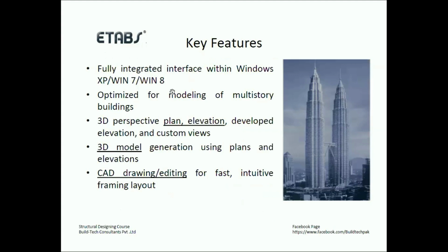Now moving towards the key features, because I already told you it's a 3D model. You can see plan views and 3-dimensional views as well. Another feature of this Etabs software is that you can import CAD drawings. For example, if you don't want to waste time in making the grids and floor plans, you can import the CAD file of those grids into your Etabs and then extrude them into a 3D model. So CAD files can be imported in Etabs after doing some adjustment in CAD.